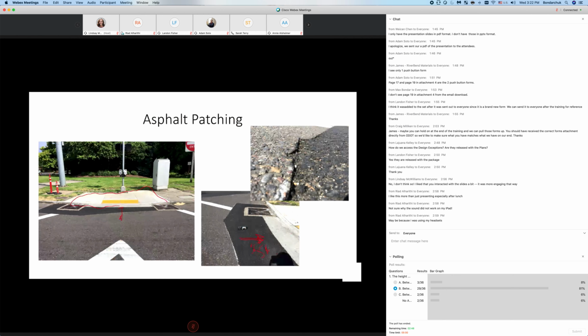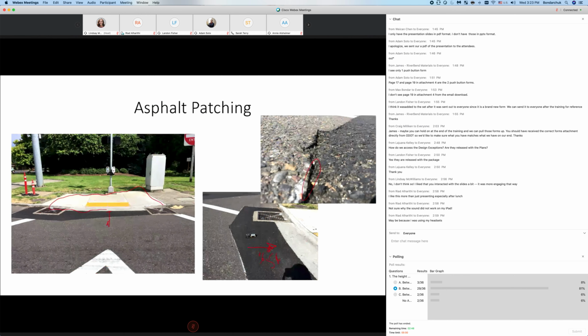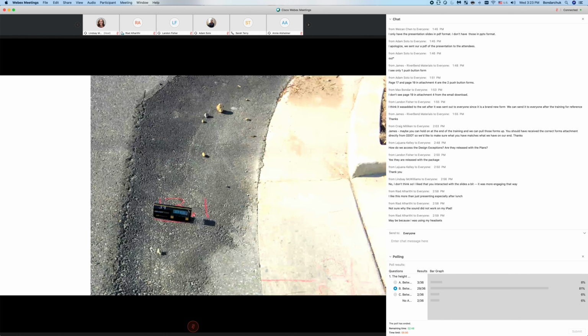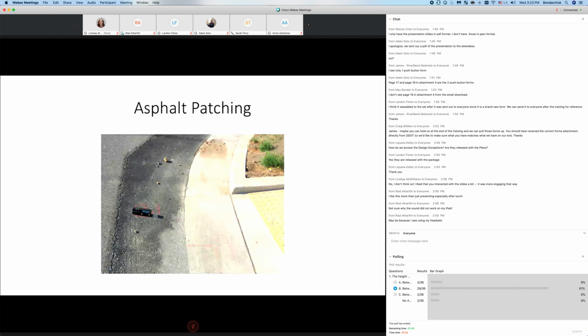And then additionally here, the asphalt patching, the lip that's causing it, that's also another failure. Should be no lip here. So it seems like we have here a slope of 13.1, which is definitely failing. It's making it worse than the existing here, so that's failed. 6.1.